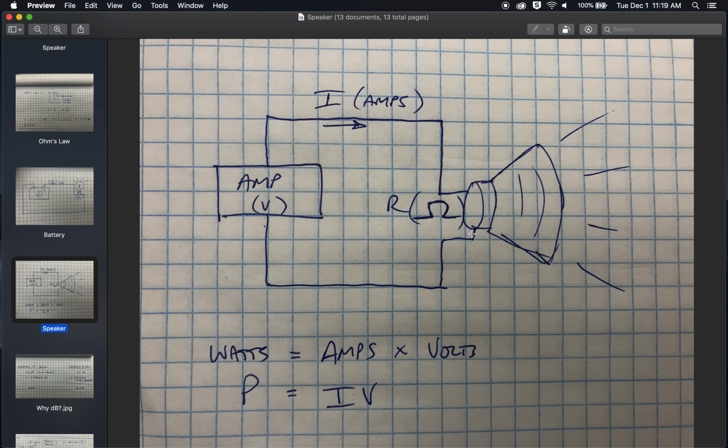or the coil in here and the housing of it can start to wear down, because the magnet is moving back and forth because of this changing magnetic field, and so that apparatus, that coil, and the housing of it can start to deteriorate over time if you're driving this too much, if it's going beyond where it's meant to go for extended periods of time.